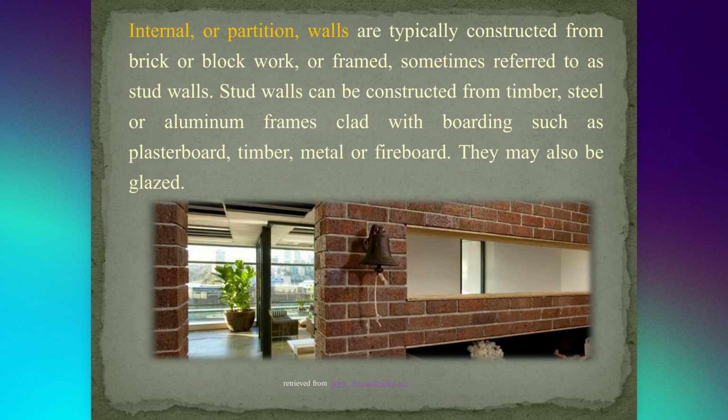Internal or partition walls are typically constructed from brick or block work, or frames sometimes referred to as stud walls. Stud walls can be constructed from timber, steel, or aluminum frames clad with boarding such as plasterboard, timber, metal, or fireboard. They may also be glazed.